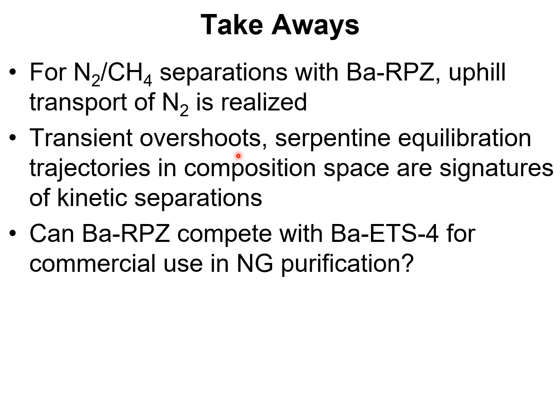From the uptake simulations, we've established that transient overshoots in the nitrogen uptake occur, and the approach to equilibrium follows a serpentine trajectory in composition space. Overshoots and serpentine trajectories in composition space are signatures of kinetic separations.